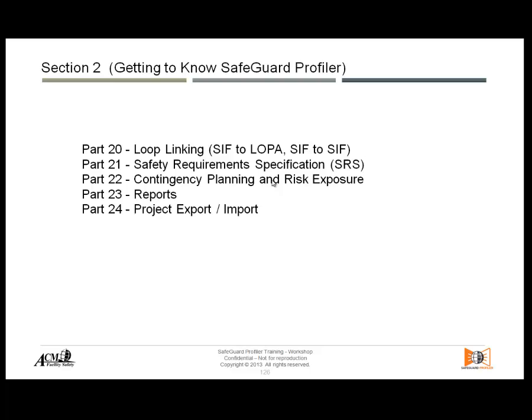Do you have any contingency plan to supply the risk reduction that you were counting on, or that was there before because it was not tolerable? If you lose that safeguard, it becomes a situation that is not tolerable for the company, then it becomes an issue, and you have to work on it. So where would you do contingency planning? You would do it at the same time as your layer protection analysis. You will spend a little more time on the session, asking what happens if we lose this safeguard, what happens if we lose that safeguard.